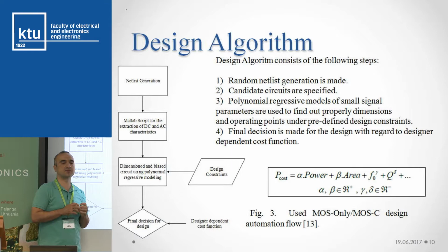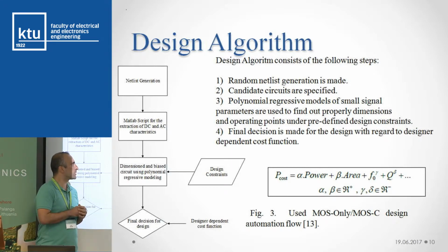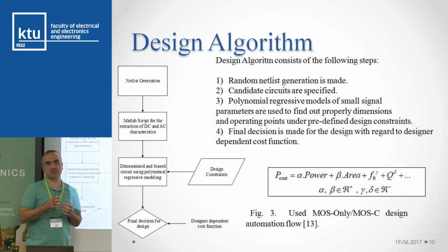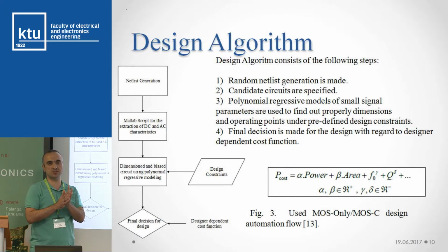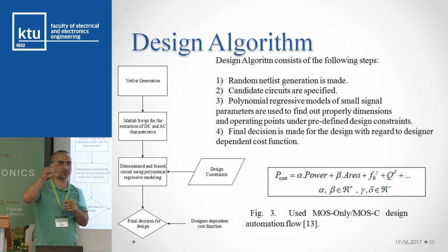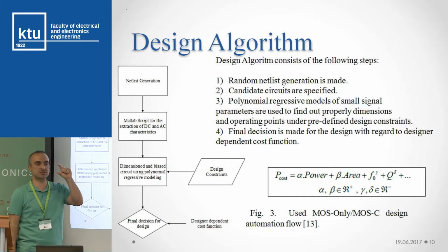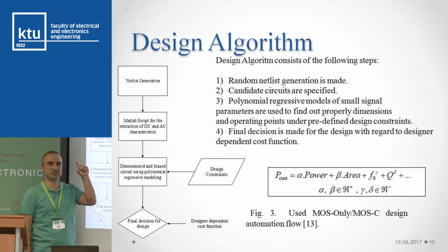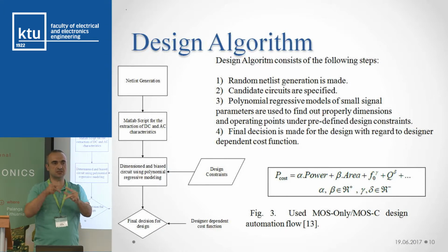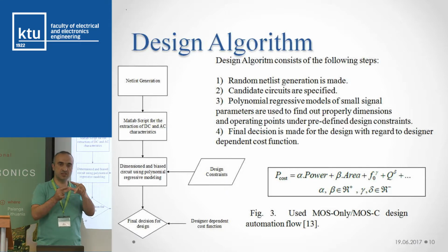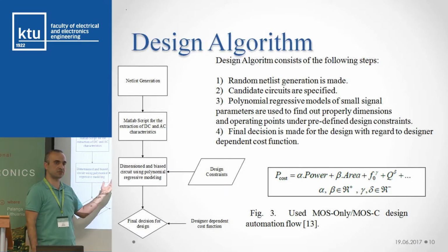First, we start with using a mathematical software tool. We model the transistor as a voltage-controlled current source. As you know, the small signal model of the MOS transistor is a gm times VGS current source plus the parasitic capacitance between gate and source, CGS. It's a 3-port device, and in each case, we randomly connect the MOS transistors. And in each case, we also generate the transfer function.